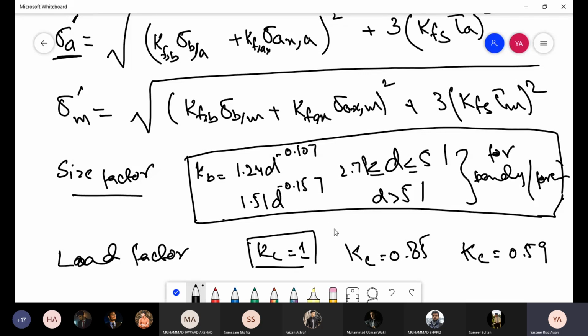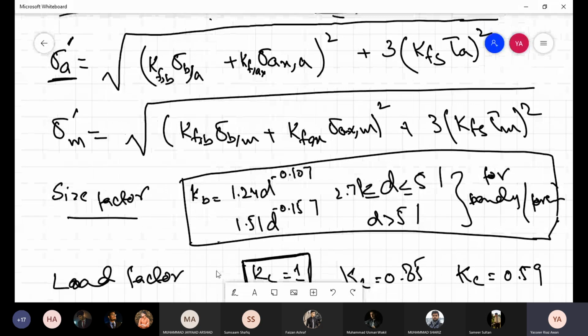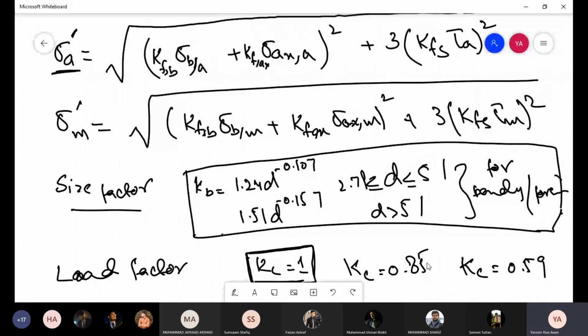Okay. What we do is we use Kc equal to 1 for combined load. Because first, obviously, we know that the von Mises stress is basically converting this whole combination of stresses into a single normal stress, okay. It's a normal stress, same as bending or axial, okay. But what we do is we take care of this factor in the stress term instead of in the strength.